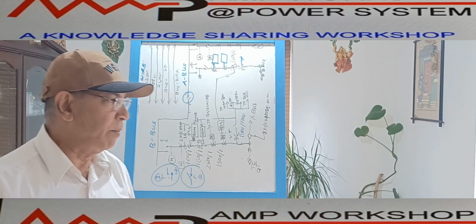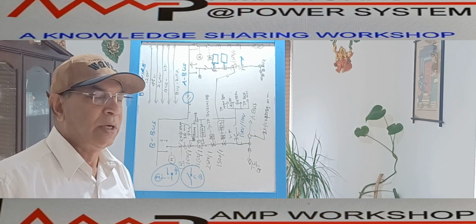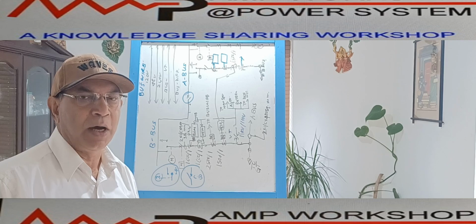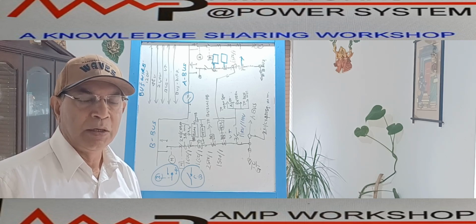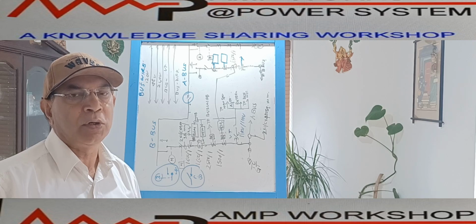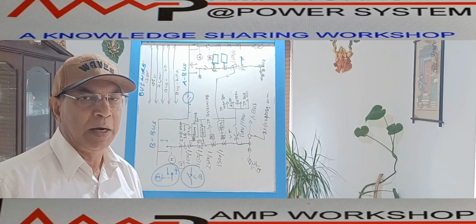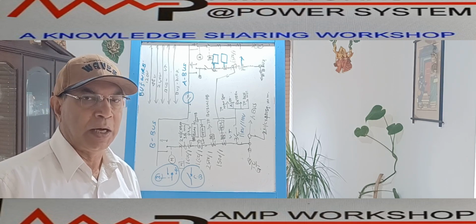So when we start to develop the switchgear single line diagram, at that moment we have in hand all the power equipment sizing calculations, including cable sizing calculation, and the overall hookup arrangement we have already planned and are aware of. Based on that, we are developing the single line diagram.